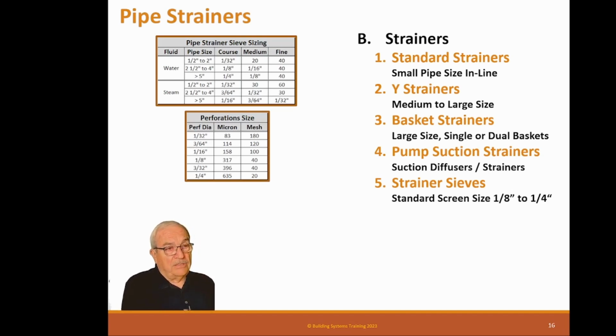Now, they make sieves down to a real small size, and you don't want to put those on a pump inlet. At the pump inlet, you want the biggest sieve that's going to protect the pump, because you don't care if small things go through, they'll go right through a pump. So let them go through.